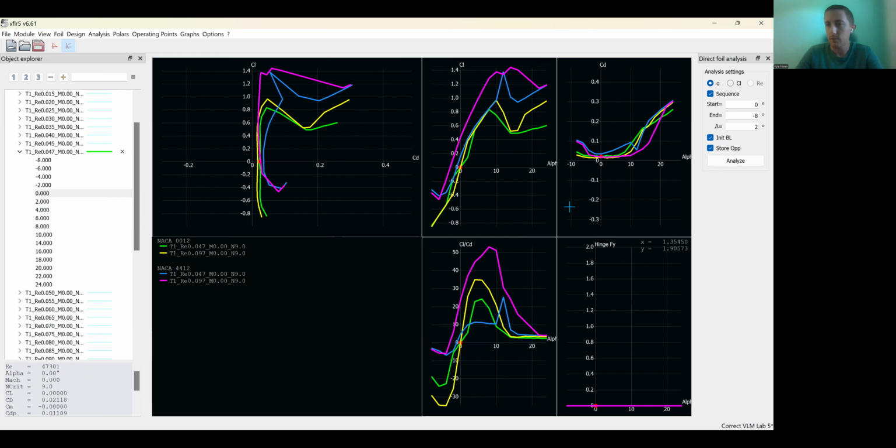If it has an error, it's going to keep the window up and tell you what it's not converging at. That's when you can play around with the actual panels that you have on the airfoils to make sure it converges. But then you run that for 47 and 97, and then you're going to populate all these graphs here.